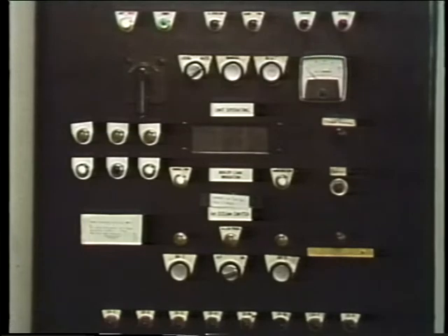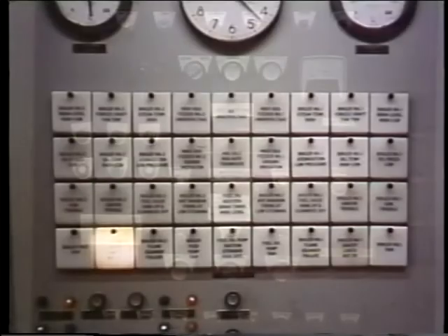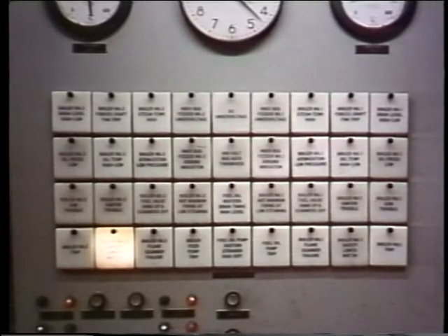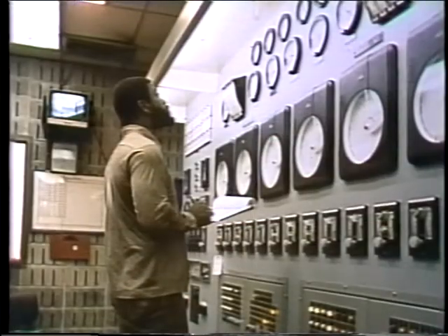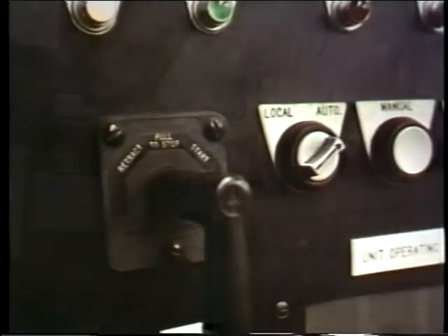Plant operators observe the cycle of soot blower operation from their controls. And the information they get on boiler operation from the gauges and readouts in the control room give them a clue to what's going on. For example, the rate fuel is burned, and the temperatures in the different passages in the boiler tell them if the soot blowers might not be doing their cleaning job efficiently. And if a soot blower doesn't complete its cycle on time, or if the blowing sequence is interrupted, it's a sure thing something needs to be done.